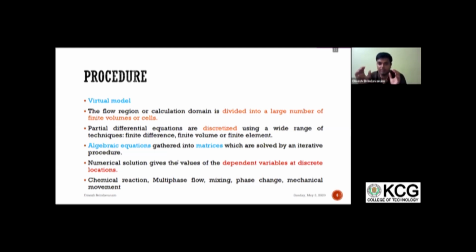Generally a computer cannot understand the geometry just from hand drawings or that sort of thing. So we need to create a CAD model of the geometry. This CAD model can be built on any platform. It can be in SolidWorks, Pro E, or CATIA. It can be in any part of the CAD modeling domain you choose. There is no restriction. But once you have generated this CAD model, you need to bring it into the CFD solver using particular standard formats only.